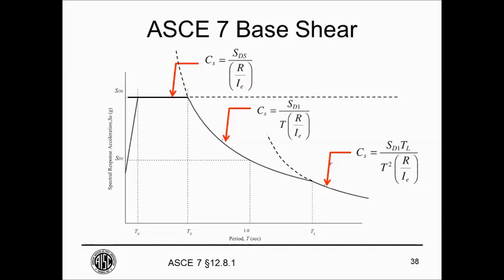Yeah, that is a holdover from older code requirements, and I think it does end up allowing things to be designed for a slightly lower force in ASD than in LRFD. So there are only historical reasons why that 20% is there for ASD, and it really is not right in terms of equivalency and getting the same design, LRFD and ASD.